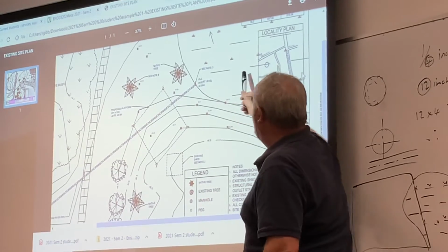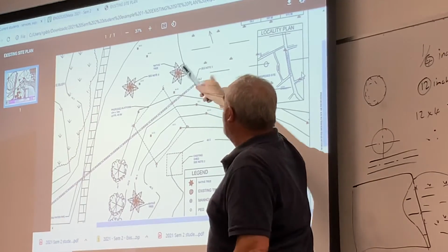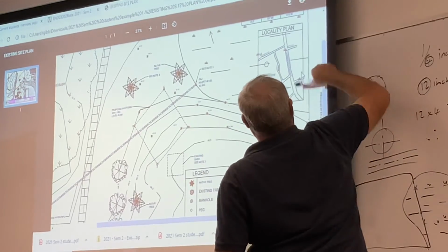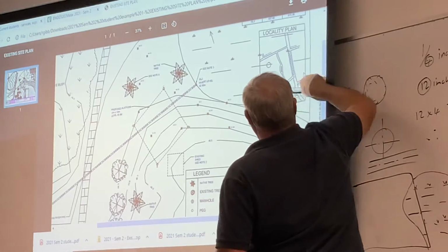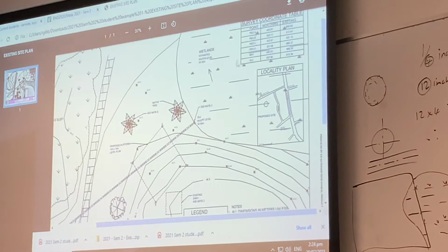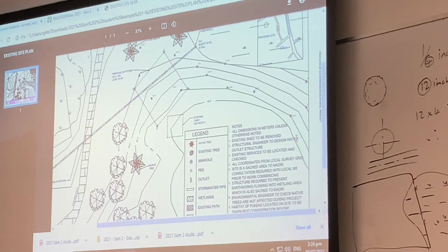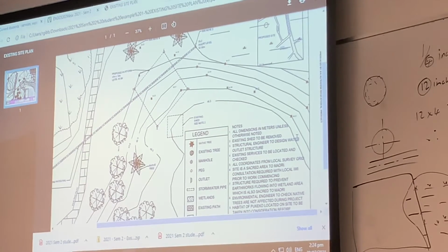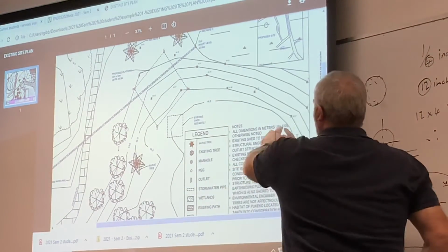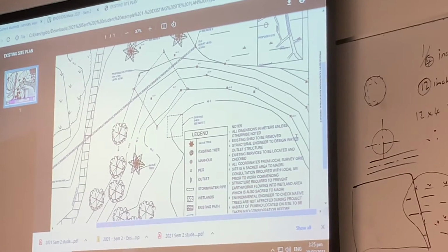Lastly, the hatch is pretty good. On this drawing, it's a little bit long, but not too bad. I probably would have approved that in class if they picked it up and showed me. Because remember, the wetlands goes for miles way over here. But they didn't cut it out of this. It goes right through here. And if you have a look up the top, it goes right through the survey coordinates, and they've also got text down the bottom over the top of the notes. I'm not saying that I will mark you down if you do this hickledy-pickledy, but at least take out some of these things to make sure that they don't cross over the top of notes.